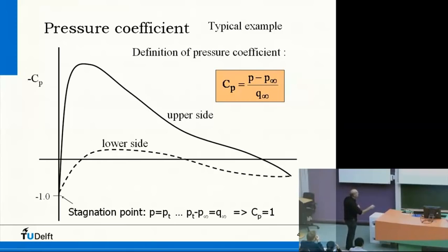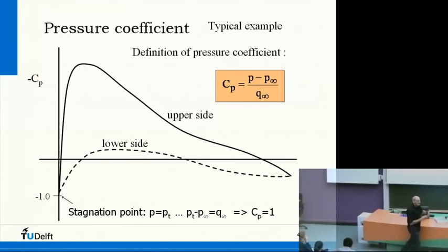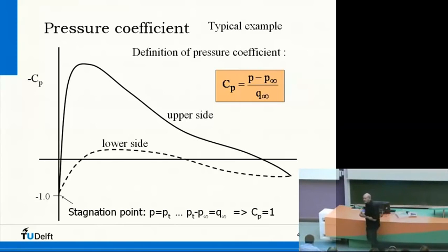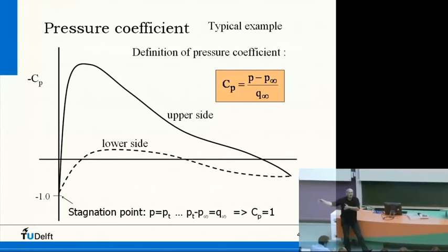And it's called the total pressure. And doesn't matter if it's compressible, it's total. And when we stop the flow, the same can be said from a reservoir, for instance, where the velocity is 0. If you remember the compressible piece about a wind tunnel, for instance, supersonic wind tunnel, then you have a big reservoir, you pump it up, high temperature, and then you release a valve, and then it's flowing to Mach 1 and further.